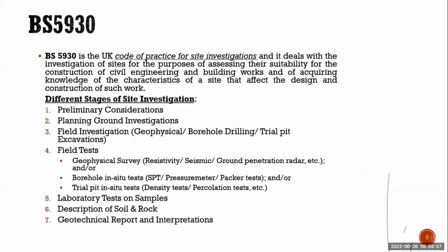And also you come to the office and do the desk study. What is desk study? You see what the geological condition of this particular site is. Is there any crater, or is any river passing nearby? Geomorphological characteristics you will also know from the geological map.